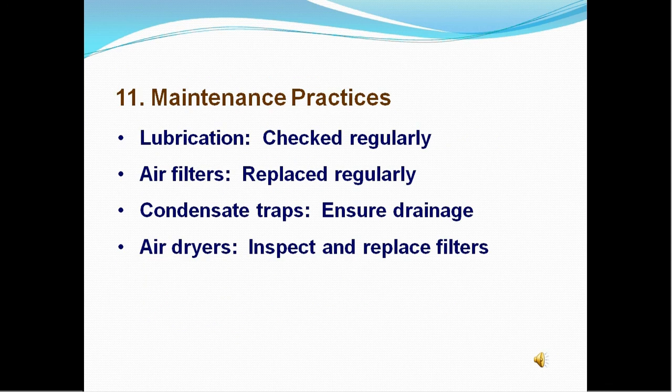Good and proper maintenance practices will dramatically improve the performance efficiency of a compressor system. Here are a few tips for efficient operation and maintenance of industrial compressed air systems. Lubrication. Compressor oil pressure should be visually checked daily, and the oil filter changed monthly. Air filters. The inlet air filter can easily become clogged, particularly in dusty environments. Filters should be checked and replaced regularly.